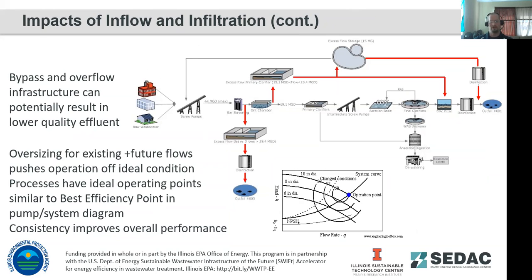This is a flow chart for a water plant that had two different stormwater bypass controls, depending on how much flow is coming into the plant. So as you follow through the process there, the first flow diversion there for storm flows is to direct through a primary clarifier and then out to an excess flow storage basin.